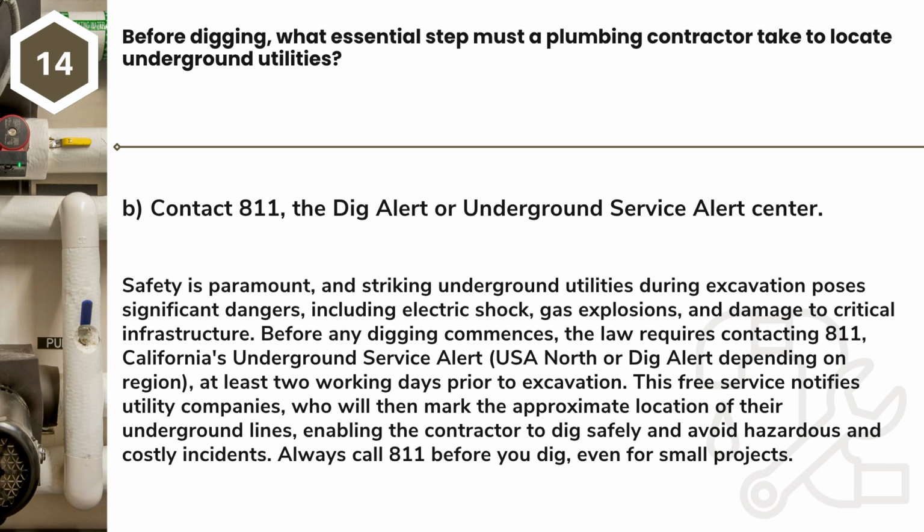Safety is paramount, and striking underground utilities during excavation poses significant dangers, including electric shock, gas explosions, and damage to critical infrastructure. Before any digging commences, the law requires contacting 811, California's Underground Service Alert, USA North or Dig Alert depending on region, at least 2 working days prior to excavation. This free service notifies utility companies, who will then mark the approximate location of their underground lines, enabling the contractor to dig safely and avoid hazardous and costly incidents. Always call 811 before you dig, even for small projects.